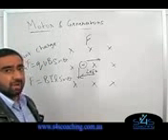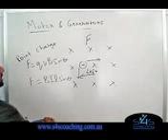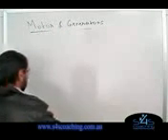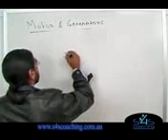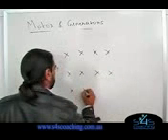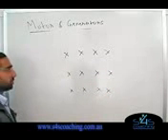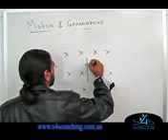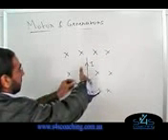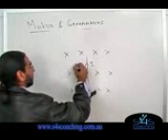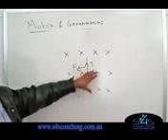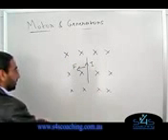Now, how does a motor work? As I said, the basic principle behind the working of any motor is the motor effect. And essentially all I do is this. Let's say I take a wire and I put it in a magnetic field. Using the example that we did previously, let's say there's a current in the wire and the current is going up. Using my right hand, B is going in, current is going up, force is going to be to the left. Now, to make a motor, all I need is a magnetic field and a wire that's carrying some current through it.